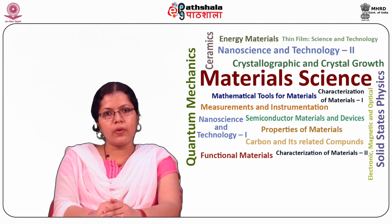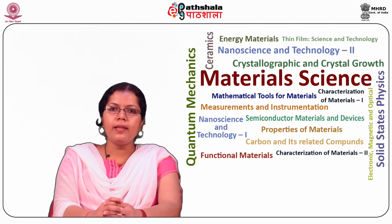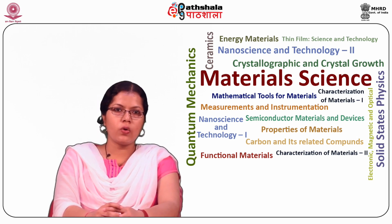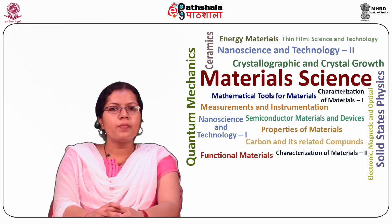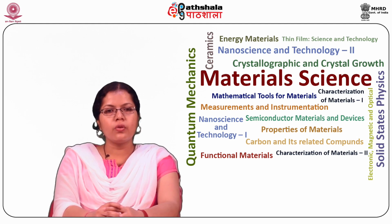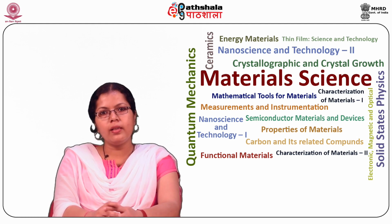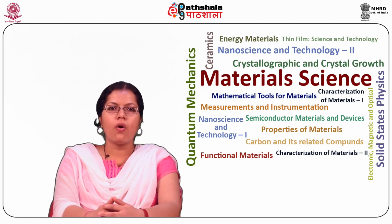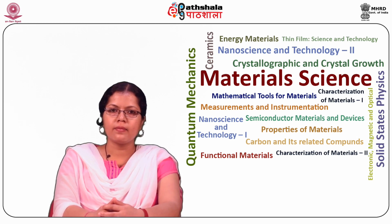Second is the moving coil. The moving coil is mounted on a pivoted spindle and is entirely embraced by the fixed current coils. A spring control is used for the movement. The use of moving coil as pressure coil is a natural consequence of design requirements.